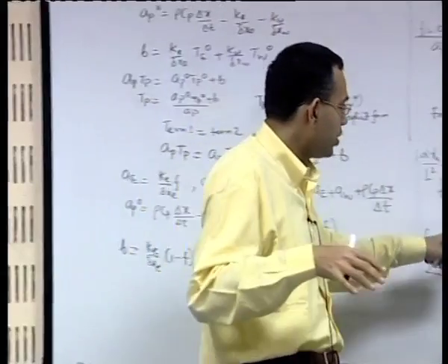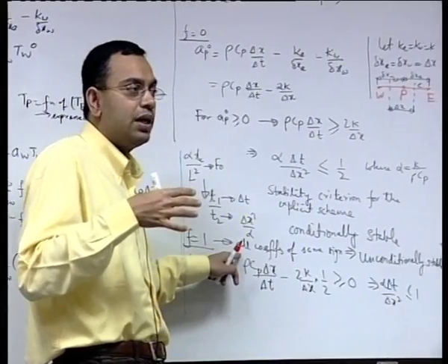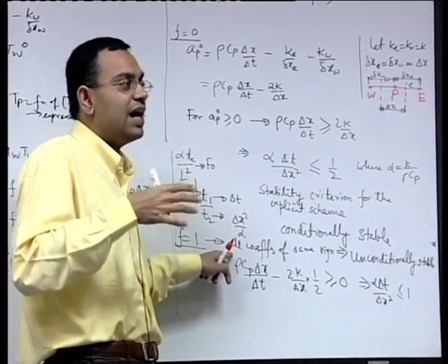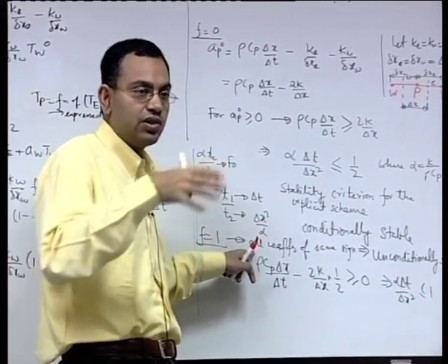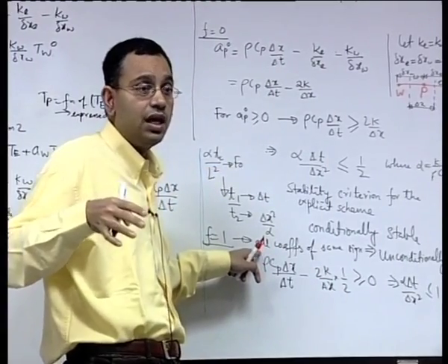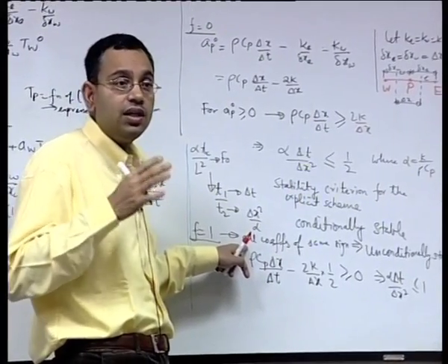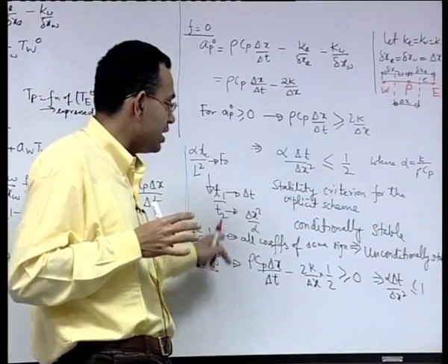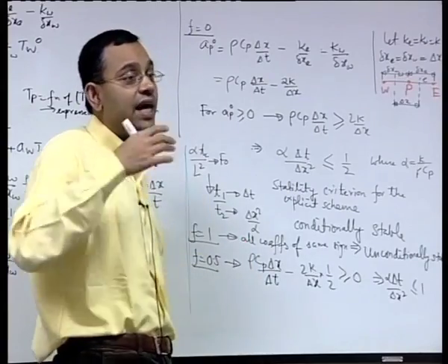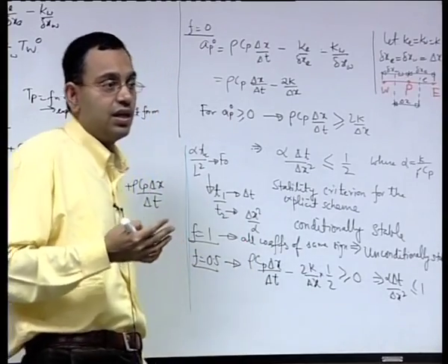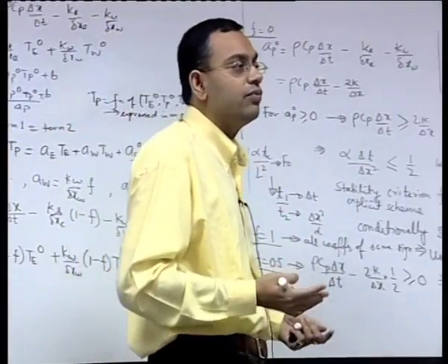So here we are trying to go beyond the mathematical stability requirement. Mathematical stability requirement will just ensure that the oscillations in the solution will die down, but once the oscillations die down, the solution is converging to something. Is it converging to the physically acceptable solution that you are looking for? It need not always be. So when you are considering the same sign of all the coefficients, you are ensuring that additional feature also, that is, you are having the solution converge to something which is physically meaningful.